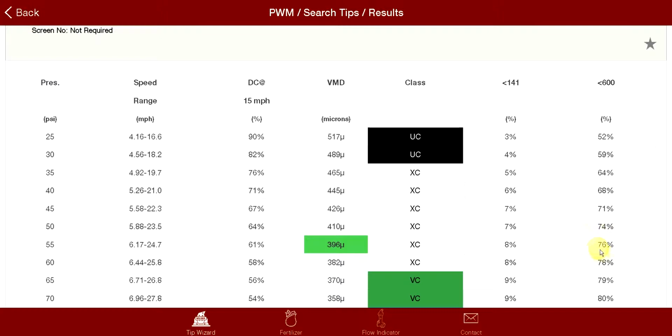With that last column there, that percent less than 600 microns, that being your coverage factor, we try to keep it above 80%. In this case, it is nominally lower, but when we do that same comparison as we did before, subtracting the drift, so 76 less 8% drift, that 68% of our volume is pretty well effective for what we want to do.